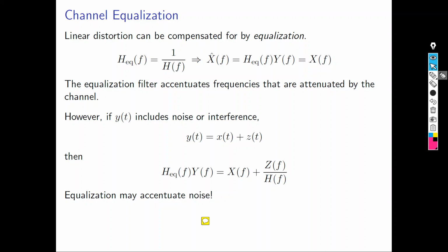If your channel is low, then noise over something low, what will happen? It will magnify it. So basically, we call this problem noise enhancement. We usually try to avoid it as much as we can because it's very bad for our system. If our system encounters this problem, then you cannot detect your data successfully.